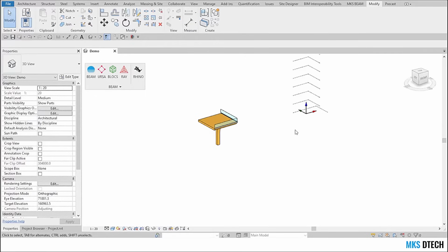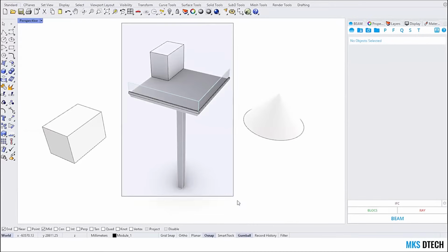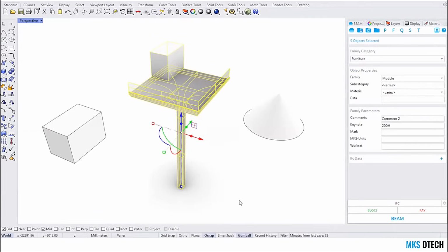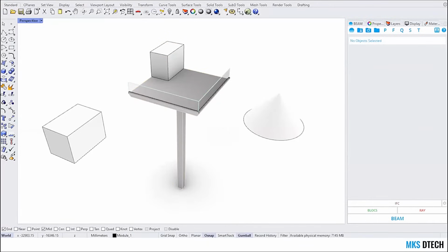And compared to maybe other workflows, it's a bit easier to have this kind of archival than having to undo a lot of operations or to change my script to go back to the version I had before, and without me having to save all the Rhino files each time, because maybe I have a big Rhino file, but I just really want to archive these objects, that I don't want to create a backup of unnecessary files, okay? Another way to use BEAM as a family.